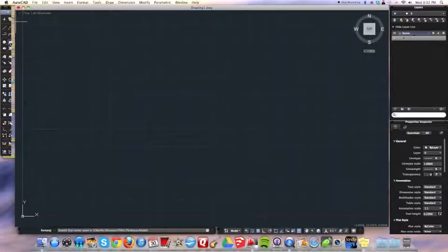So I'm going to click on the rectangle, and I'm going to create a rectangle somewhere on the grid. Doesn't really matter where. I'm going to start the first corner by clicking. I'm going to start moving down, but I'm going to tell the program that I know the dimensions of the rectangle, so I'm going to hit D, enter, because that's one of the options on the status bar if you look on the bottom. Okay, and the length of the rectangle, that's going to be the X. I want that to be 4, enter, and I want the width to be 3, enter.